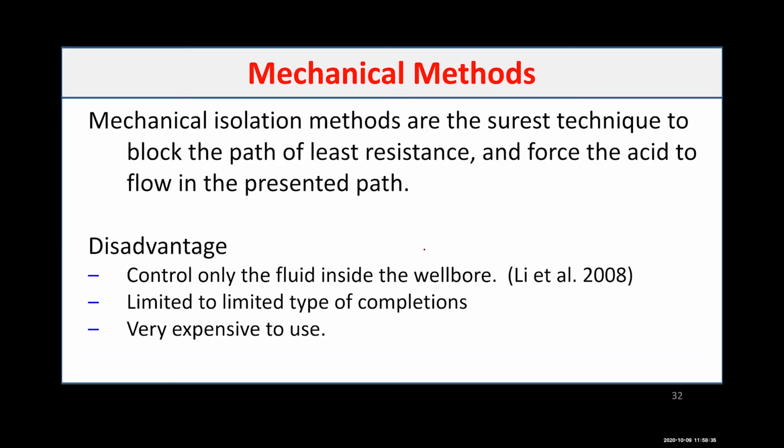cement, a certain type of completion. You need to have casing and cemented most of the time. If you have an open hole completion, a lot of this mechanical method does not work pretty well. It controls the fluid only inside the wellbore. When it goes to the formation, you don't have any control.